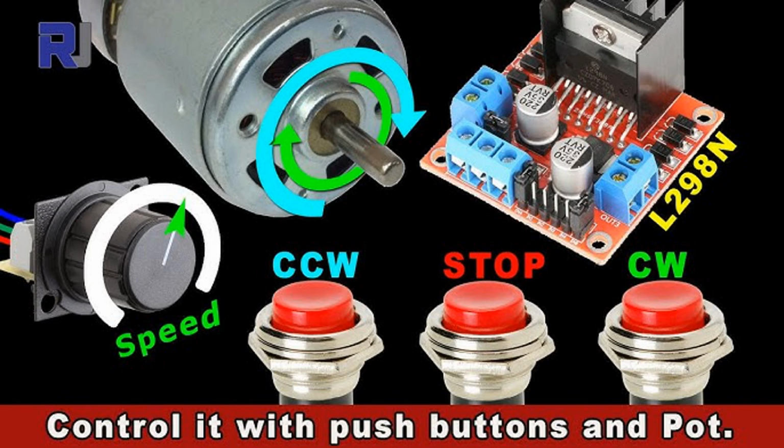1. Unipolar stepper motor drivers. Function: Unipolar stepper motor drivers control motors with unipolar windings, where each winding has a center tap, allowing for simpler current control. Operation: These drivers energize the windings in a specific sequence to rotate the motor in discrete steps. Typically, only one half of the coil is energized at a time.